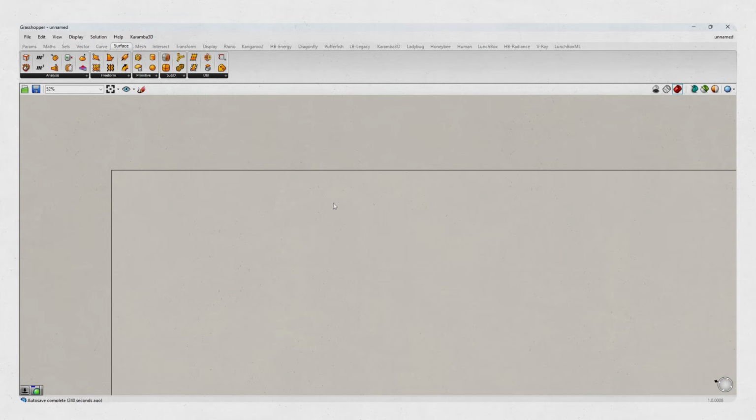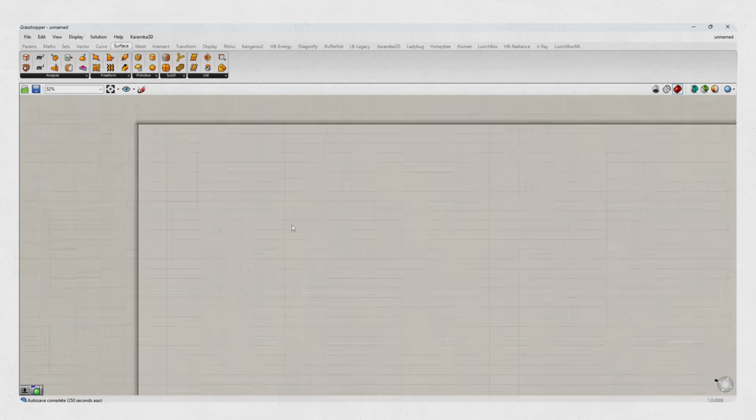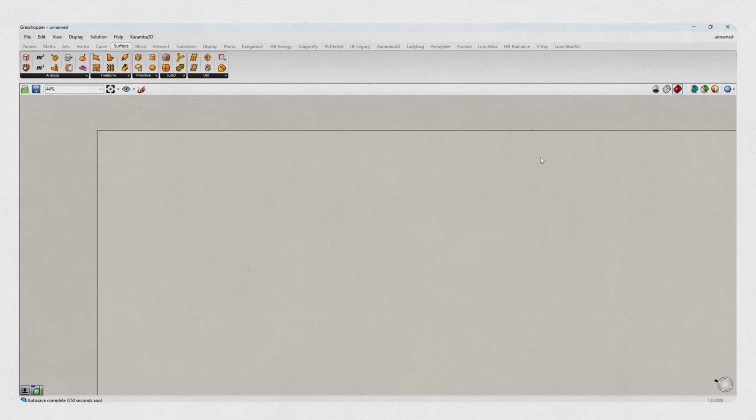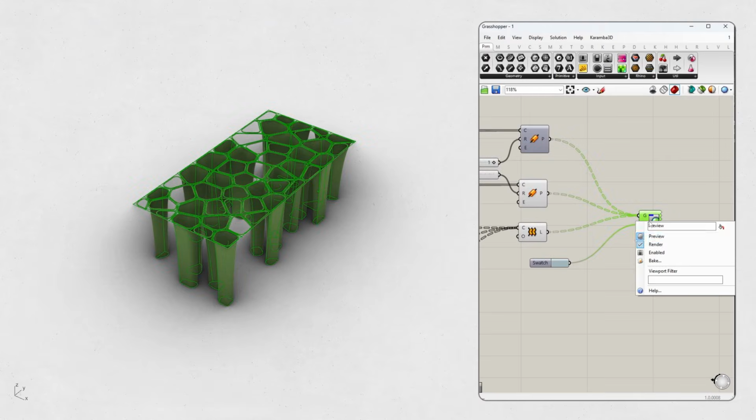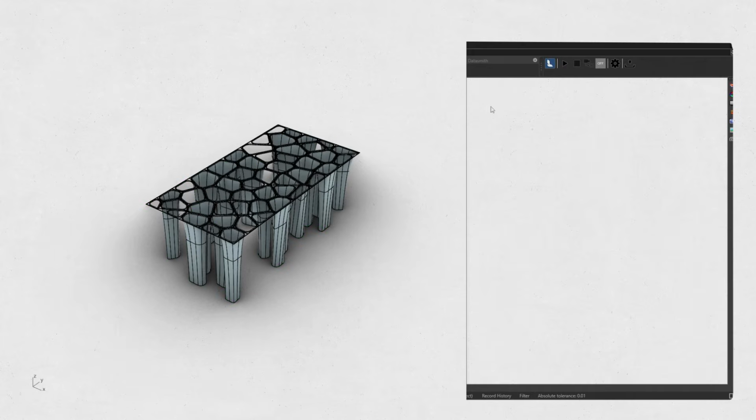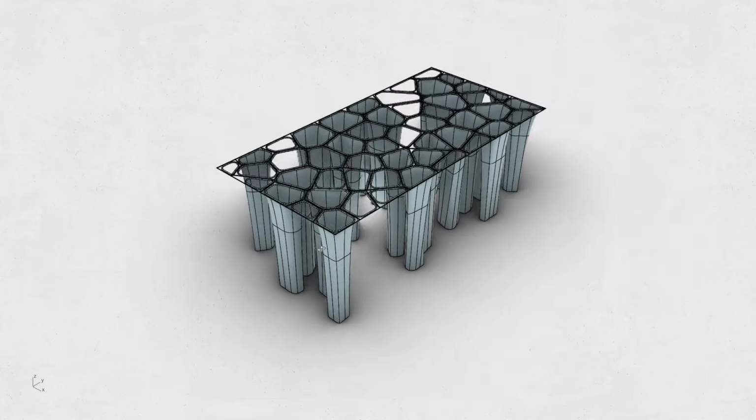Here's a super important point. Anything you create in Grasshopper, until you hit bake, is virtual and dynamic. That means a real Rhino model isn't made yet. It's just data-dependent geometry that keeps updating as you change the inputs. Baking is turning that parametric model into a real, independent object inside Rhino.